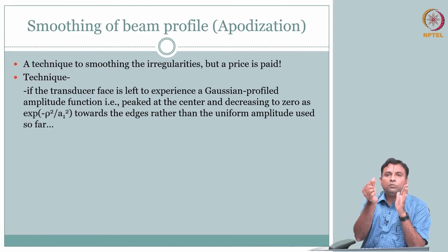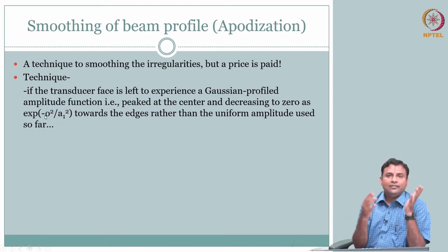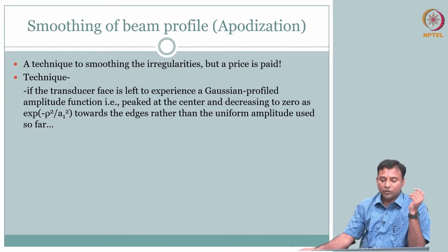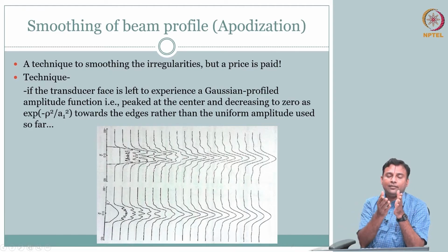So I can have a sound absorber, more sound absorber at the corners and less sound absorber at the center, and I can have a profile of that. It can change from no absorption to high absorption in, say for example, an exponential fashion, which is kind of your windowing. Okay, so instead of this rectangular, I can profile it. I can come up with a material, say a sound absorber.